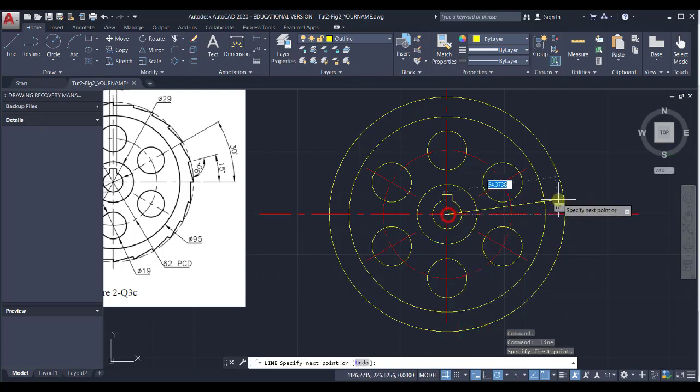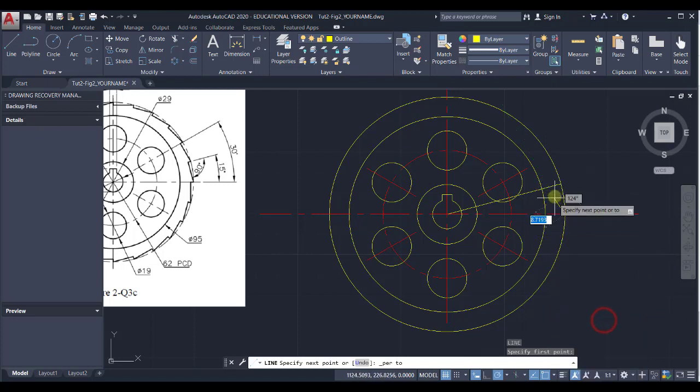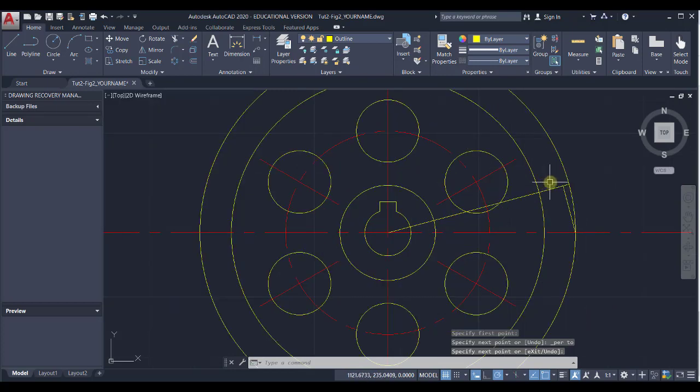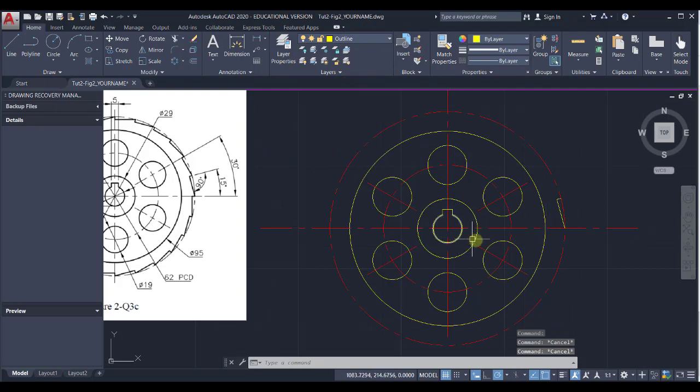Click on this, click on here, and just move up until you see the infinite green line. Come near to the circle, just click on this point. Next thing you need to do is click align again, starting from this point, and here you just shift right click, say I want to be perpendicular to this line, spacebar. Once done, you can trim this. Just trim it away like this, convert this to a center line, and perform the array.